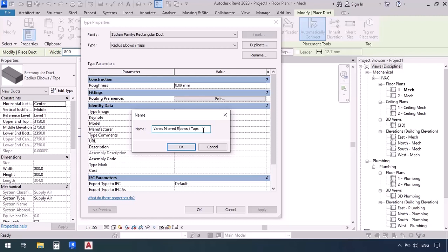And well, at the end of the name, in case we want to use some junctions on the duct, I'm going to type in fillet T. We would want to put a T with fillet or round ends. And actually in this selected type, the corners were T-shaped, but now we want to put fillet instead. And then I'm going to add transition 30 degrees. But there's really no need to put a really long name. I only wrote this one as an example, so you would know that you can add whatever you'd like.